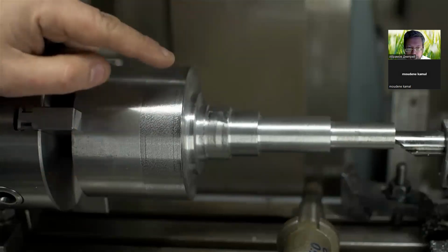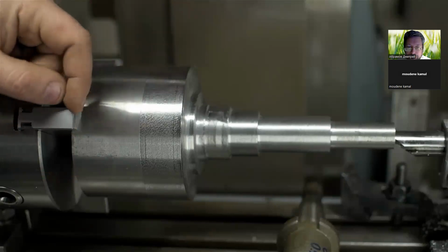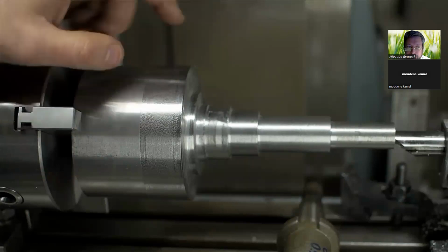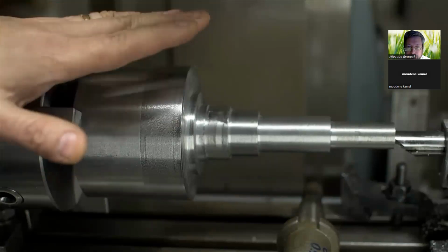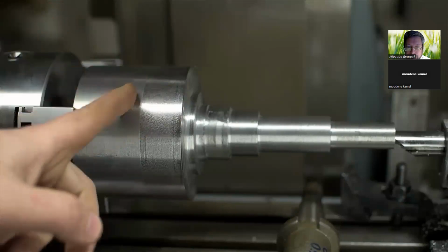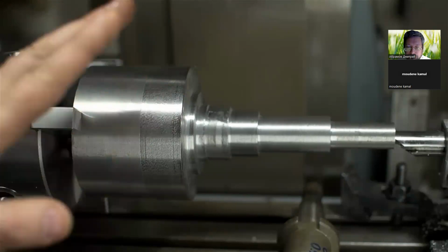The 1.5 thou I'm seeing now is from their 3-jaw chuck. I mean, maybe a little is coming from this 3-jaw too, but I bet most of that was just their chuck and working off the OD of raw stock, which is fine. They also took a skim cut here on the large diameter, and if we could cut the back of this part off, we could grab that and be in a better situation, concentrically speaking.